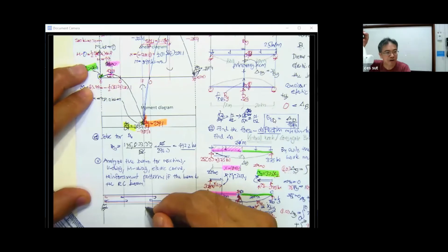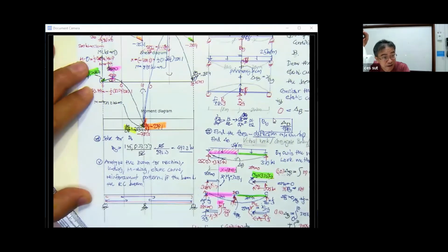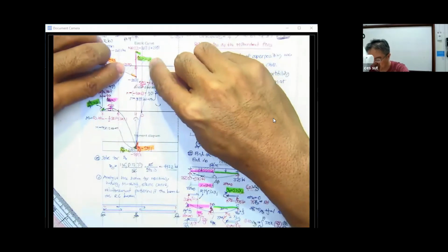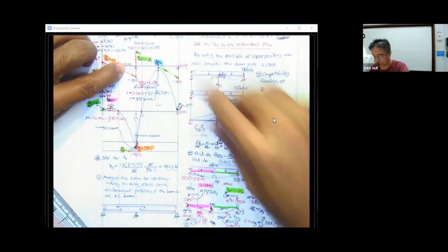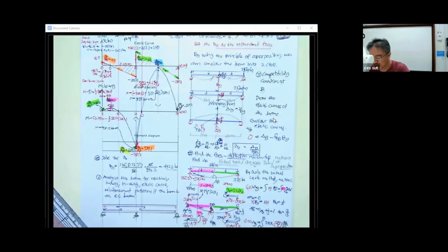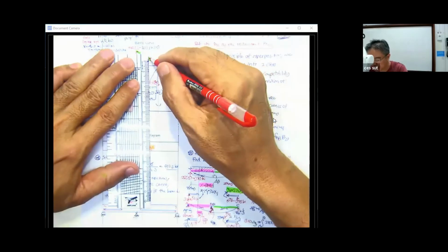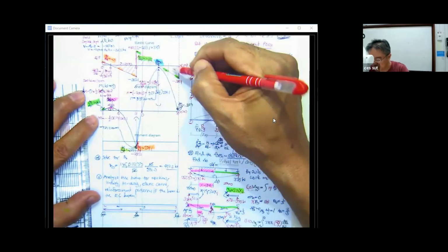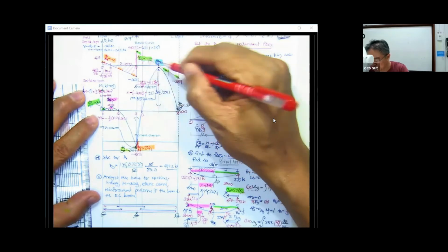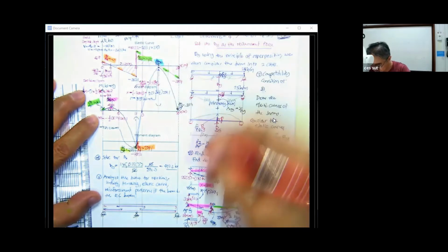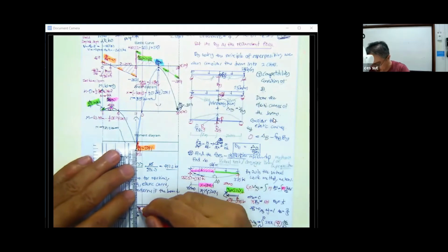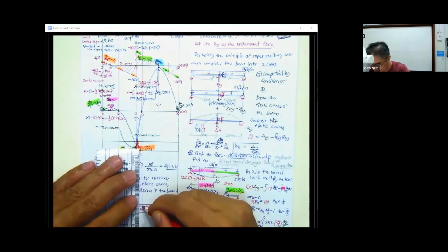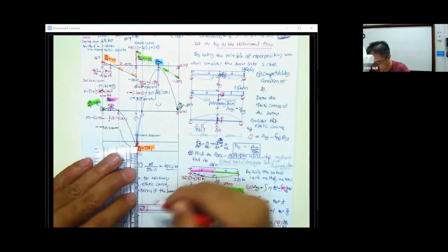And then we also need to consider the shear force, and you can see the shear force is distributed unequally, and the large shear force is in this area. So most of the time, if you prefer, you're supposed to separate the reinforcement of this beam into this portion and this portion, and the stirrup on this way and this way is supposed to be the same. It's going to be more stirrup in this area. This area must have more stirrup. Okay, the spacing between stirrups is going to be very close.